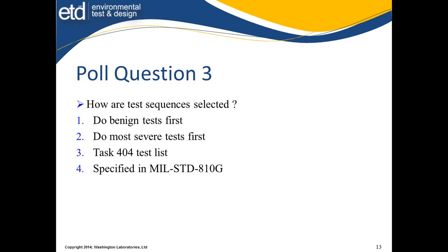The idea is that the test article shouldn't be dealing with one test and one test only with a different sample for everything else. We need to examine, does heat cause immersion gaskets not to perform well? Do vibration tests cause cracks that leak during immersion or rain? Things where one test can contribute to the failure or success of a different test should be considered. And we need to build our test in that sequence.